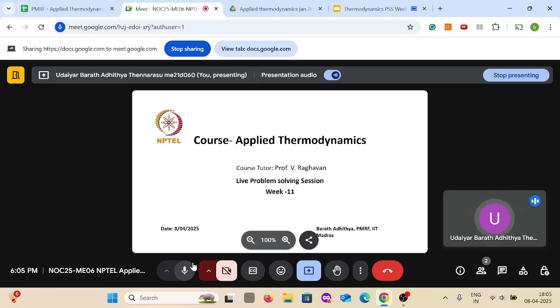So you are basically measuring your stagnation temperature. So from a measurement point of view, it can create errors, so you have to take these effects into account, but in general we assume when you are bringing this velocity isentropically to a state of rest, or velocity of 0, you call those properties stagnation properties.